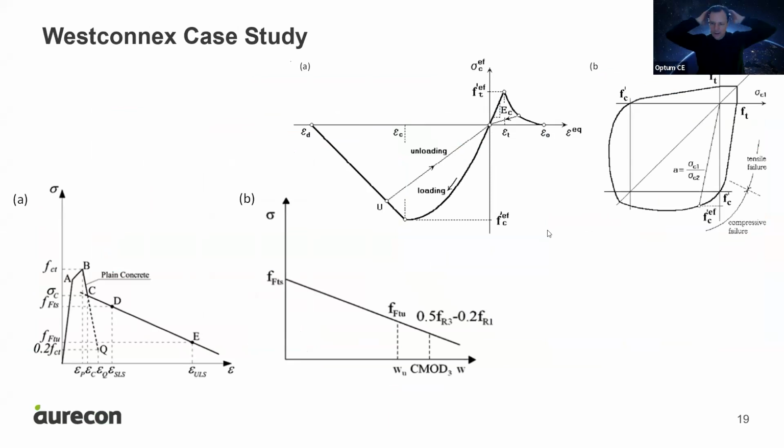So the constitutive model, if you look at this, the B on the top right hand corner there, that's a biaxial state, but you also have the triaxial state. I've only shown the biaxial here because it's more familiar and more commonly used. But the B here is actually in biaxial state. So once you get the other confinement in the other direction, you have an enhancement of your compressive strength. That's a famous simplified model by a German researcher from the 1960s, Kupfer. That's how the biaxial or confinement enhancement is included in the model.